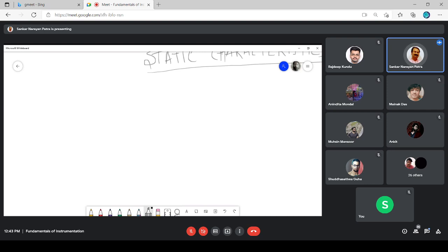For that you will take certain measures, and finally your instrument is modified and now it can show you 100 degrees centigrade where the boiling point is exactly 100 degrees centigrade. So that means there is no error, or the error is 0. This kind of measure is called static calibration, or calibration. I'll come to the definition of calibration in detail, but this is a kind of calibration we did, and finally that instrument is ready to use.